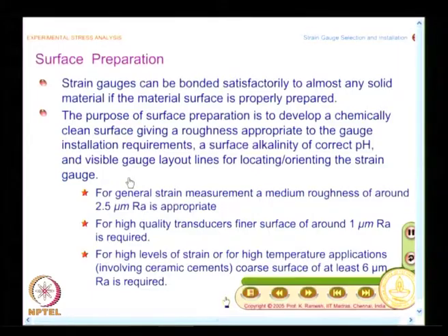See, this is very important. When you say in an actual structure, I want to measure strain, how I have pasted the strain gauge at the point of interest matters. So, I must align it appropriately, because strain gauge essentially gives you component of strain along the gauge length.